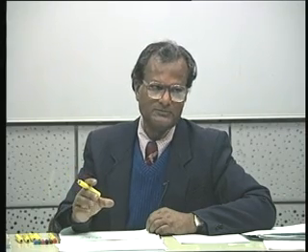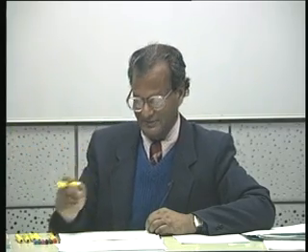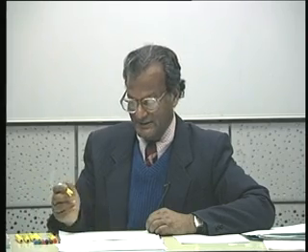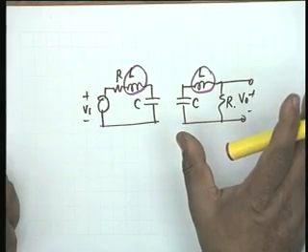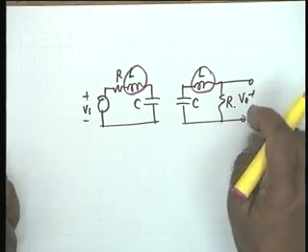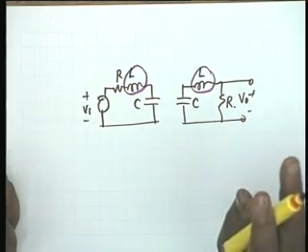Most of the coils that you see mounted in radio frequency and lower frequency apparatus are all shielded, because otherwise they are going to couple with anything that is nearby and cause havoc. So, they have to be shielded. If there is no coupling between the two, obviously V0 shall be identically equal to 0.